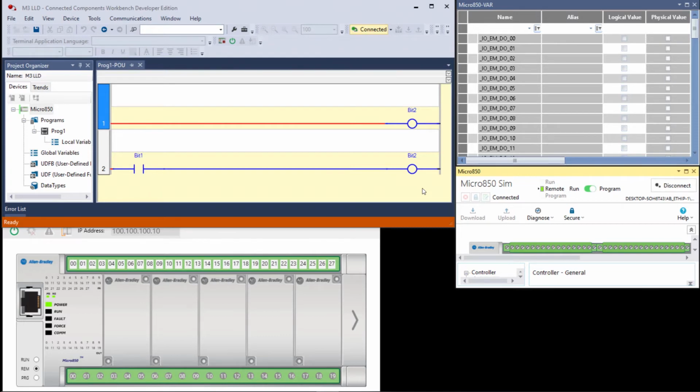And the questions, the instructions are always true or false, but never on or off. Understand this or it will hinder your ability to work with ladder logic diagrams. Is rung 1 true or false? It's true. In the run or the program mode, it reads true. It's not executing right now, so it's not executing true, but it reads true.